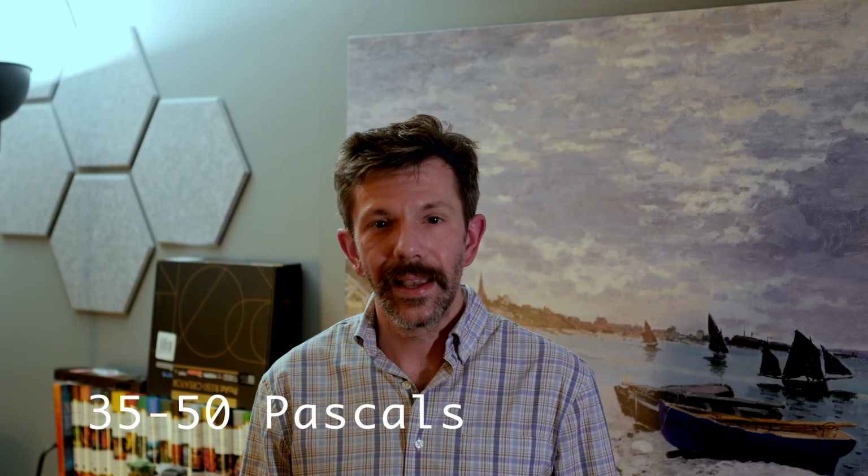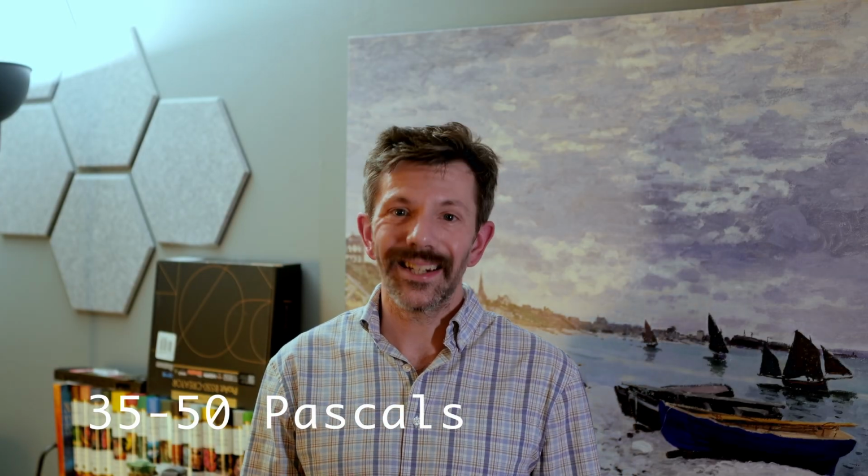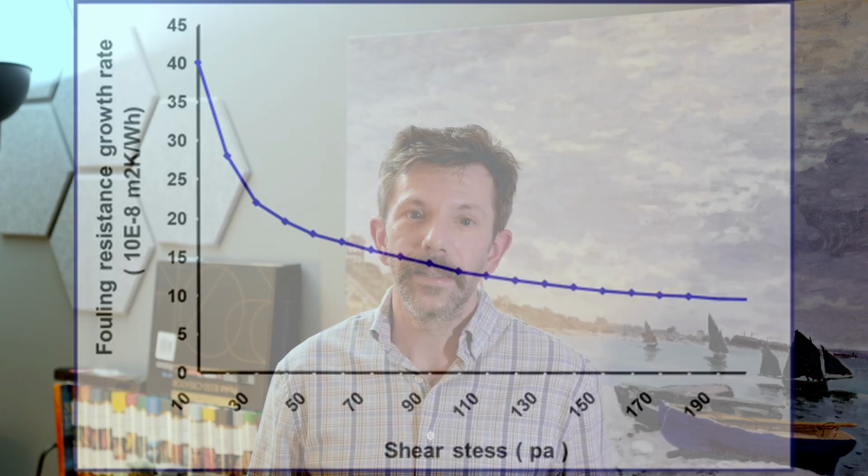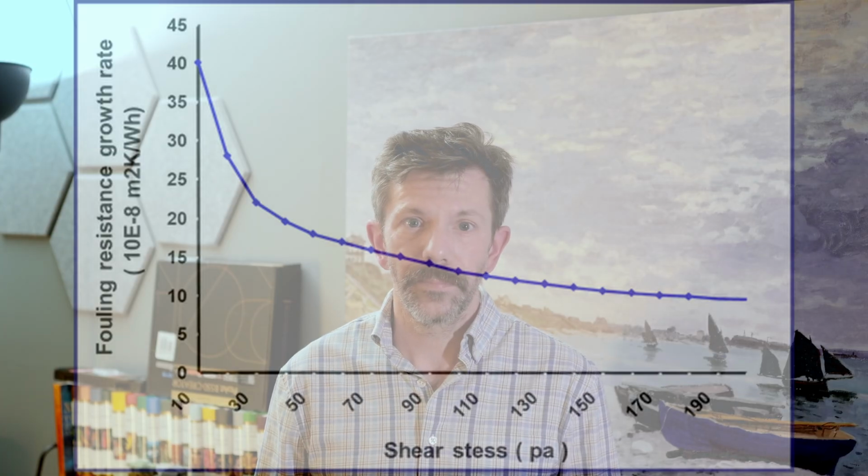By maintaining a high level of shear stress against the channel plates, particulate deposition is reduced by an order of magnitude. When you oversize a heat exchanger, this turbulence and shear stress will necessarily be reduced, which will increase the risk of fouling in the first place. And if you're thinking, I bet that's also nonlinear, you'd be absolutely right. So oversizing the heat exchanger will only serve to increase fouling risk and therefore increase maintenance intervals.